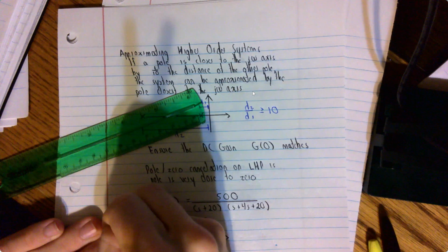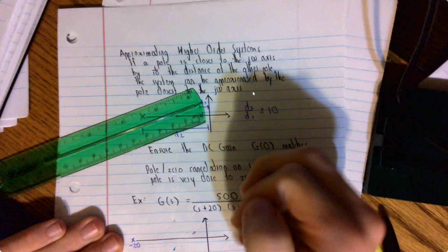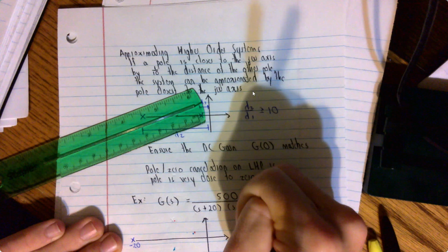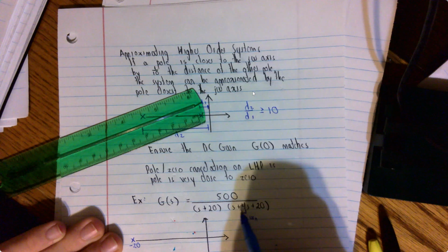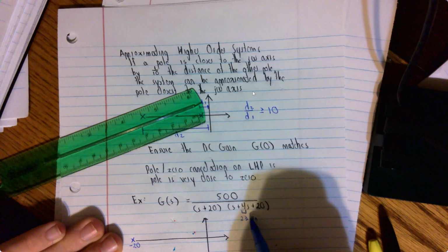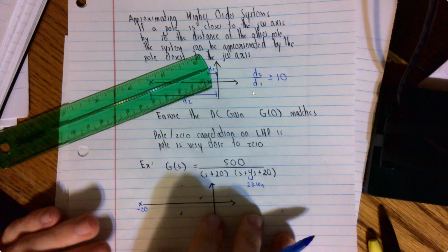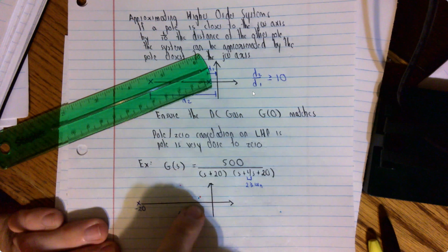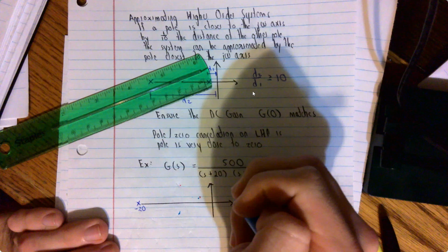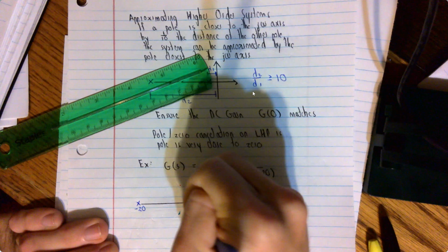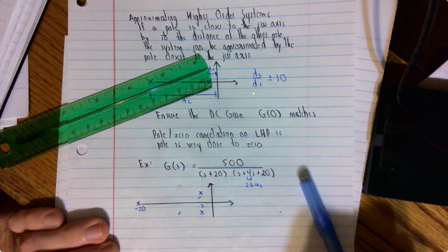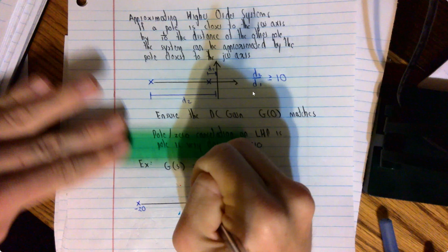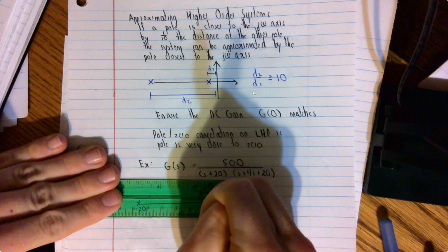And then here, remember that this term is 2 zeta omega n. And so your zeta omega n is 2 from this, because 4 is equal to 2 zeta omega n. Zeta omega n would be equal to 2. So remember, on this, it's negative zeta omega n. So at -2, you're going to have your complex conjugate poles here. So these would be two complex conjugate poles at -2. Well, if you look at the distance between the two, the distance here for D1 versus D2 from the j omega axis.